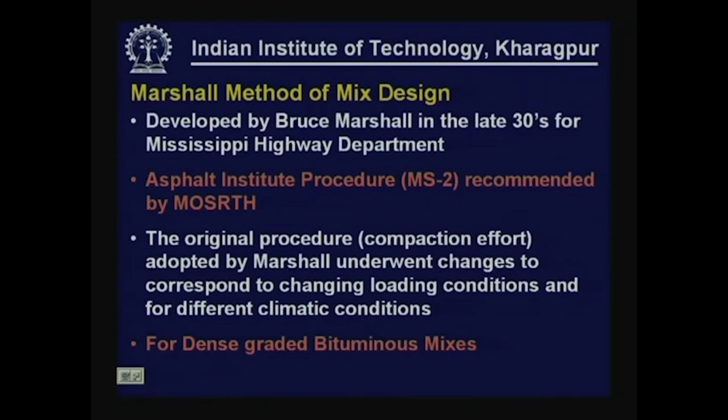Ministry of Shipping and Road Transport Highways recommends that the Asphalt Institute procedure manual MS-2 should be followed for design of bituminous mixes. So, most of the provisions that we are going to discuss in terms of Marshall mix design will be as per Asphalt Institute procedure.